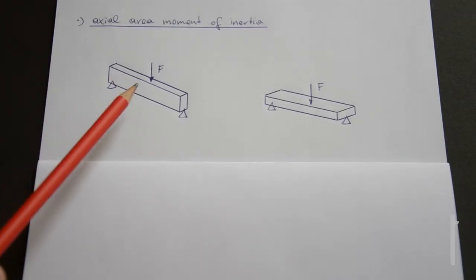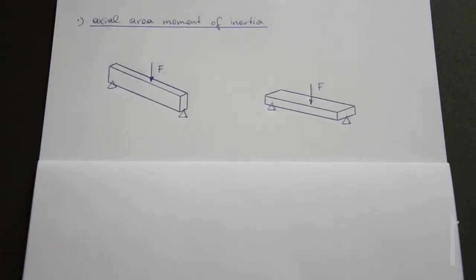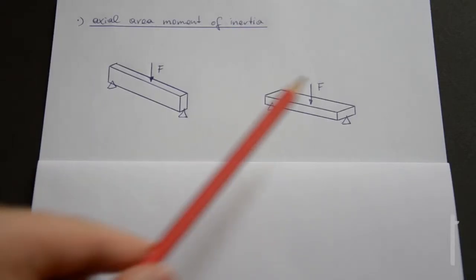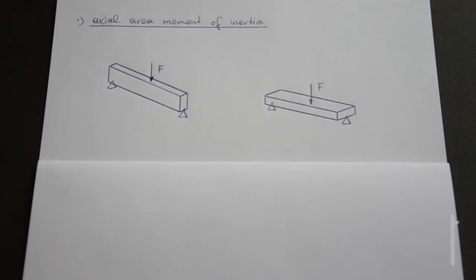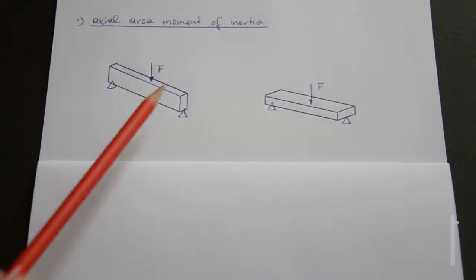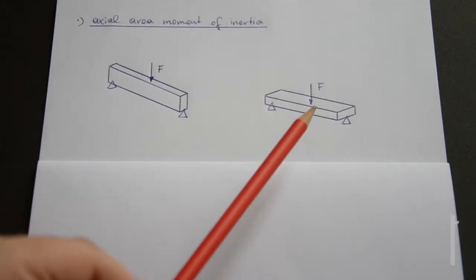Okay, this is a board or beam which rests on these 2 points here, and it is loaded with the force F. Now, in both drawings we have the exact same board and the exact same force F. And the question at hand is, in which one of the two systems will the board bend more? Well, of course, this isn't a hard question, and it is likely that most of you will have an accurate idea about it, because it is the board on the right side. The reason for this is the area moment of inertia, which is bigger in the left situation. Okay, so the resistance to bending is bigger in this system, so this one will bend more.